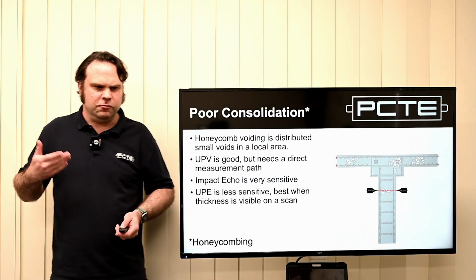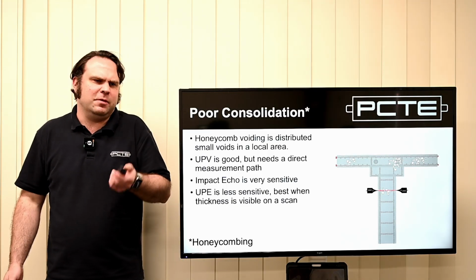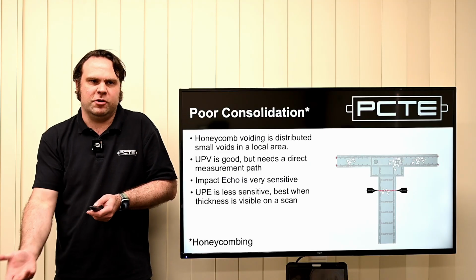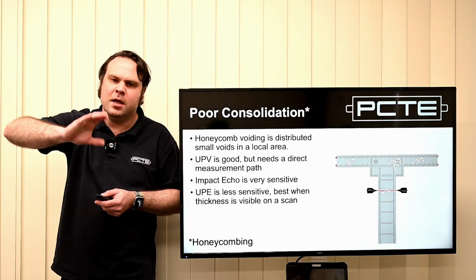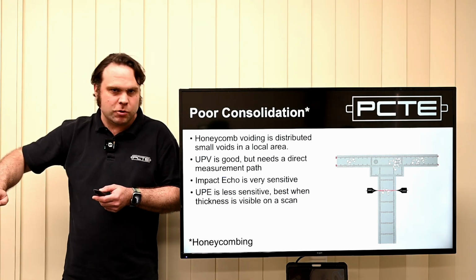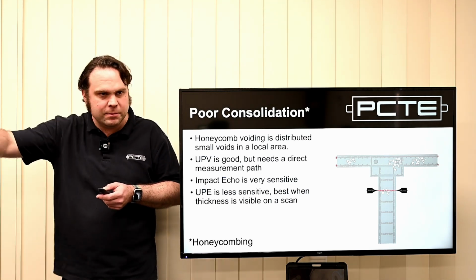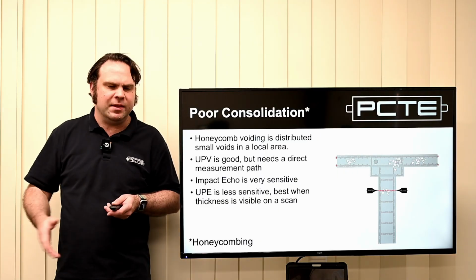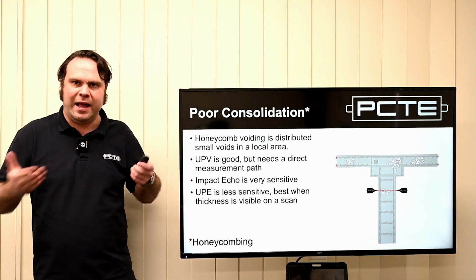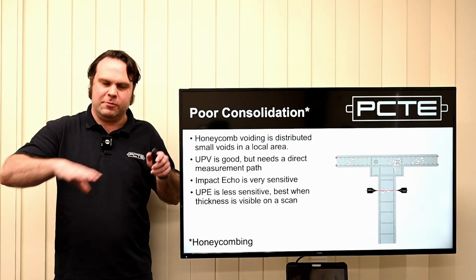Now, if it's really, really bad, sure. If it's got big blocks of nothing, radar will work. Bondek, not Bondek, I apologize. Some of your plastic formwork systems or your cement fiber formwork systems, if they get really empty, yeah, you can use radar to find voids in there. That's quite commonly done, as is thermal camera work, a bit beyond the scope of my presentation.